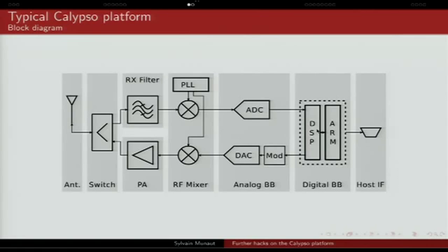If you look at the transmit path, so how the phone actually transmits bursts, it's pretty much the same thing, except in reverse. That is, you send data to the analog baseband, it's up-converted, then it's amplified because you need to transmit with some power to actually get to wherever the antenna is, and it's sent to the antenna.